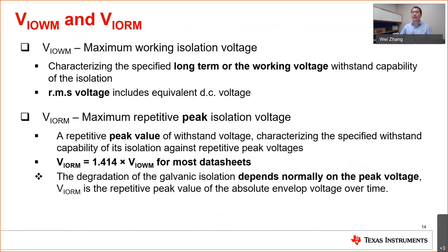And VIOWM and VIORM, you see here, it is not a routine test. It is a type test. That is pretty much verified by either TI internally or by the certification agency. So VIOWM is working voltage. It is really telling the long-term working voltage withstand capability.